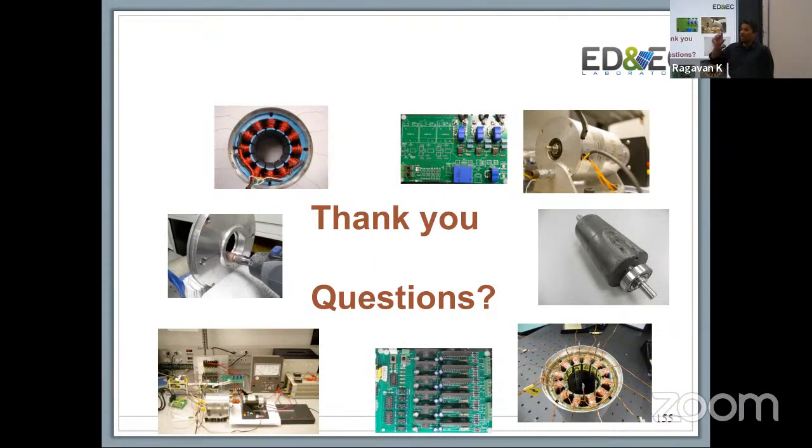Otherwise, let's say you have an interturn short and your inductance on one of the phases is lower than it should be because you have fewer turns. Inductance goes as N squared over reluctance, so N went down and your inductance went down correspondingly. Then in Ri plus L dI/dt, since it's a small inductance, you end up getting a change that is much faster than you would normally have expected.